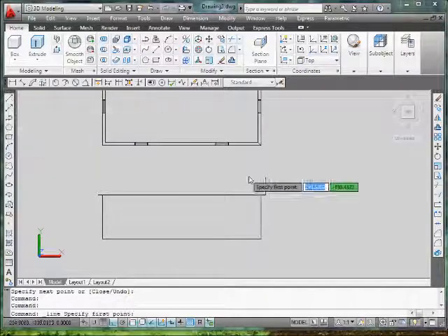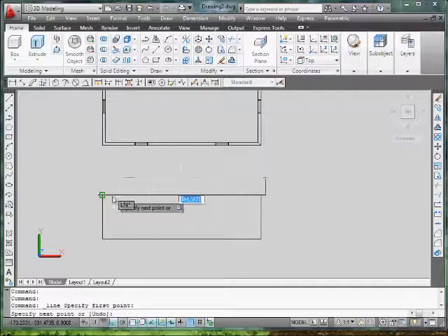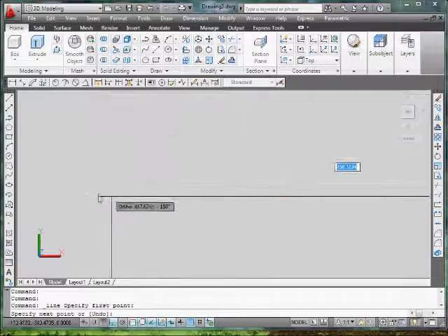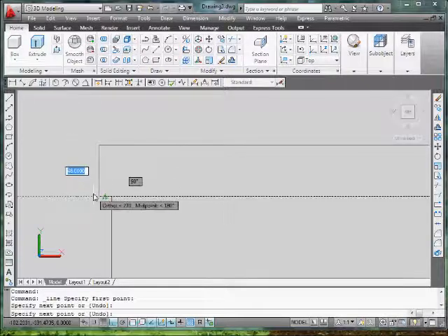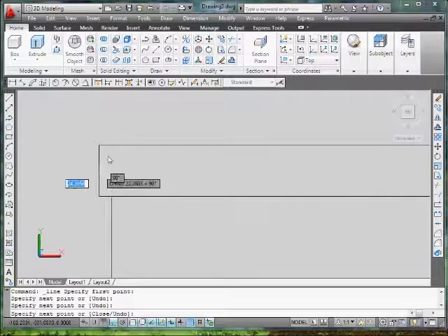Let's have a line, I'm drawing a line to close this box. What I can do, if I move my mouse to the endpoint over here, and I move my mouse up, it will actually draw this reference green dashed line that emphasizes that your line is perpendicular to the endpoint at the bottom. So you just can click, it'll be perfect, and then close it up, or you can type in C maybe, like that. That's one option.